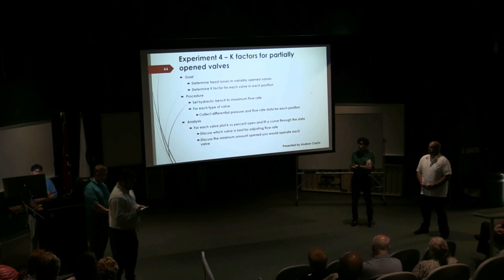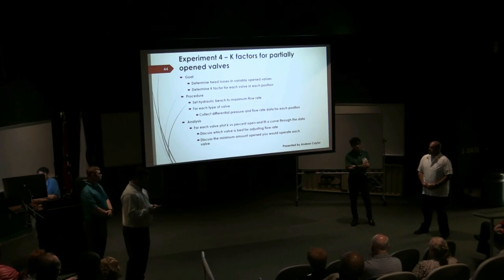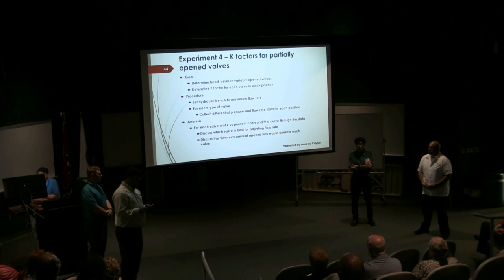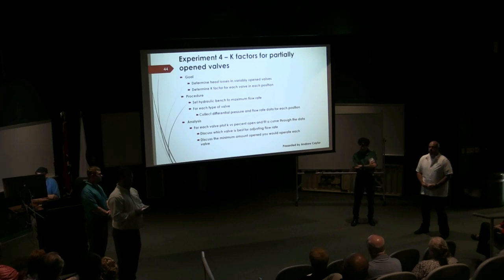For this experiment, we used the same valves but only partially opened them. We measured head loss and calculated K values at different openings. We were able to plot percent open versus K value to see which valves are best for adjusting flow.